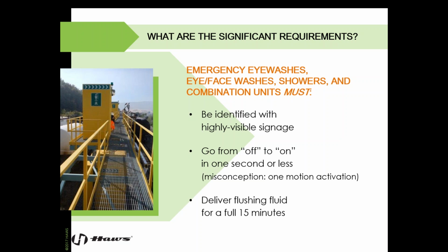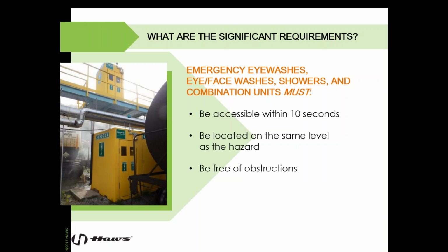All equipment needs to deliver flushing fluid for a full 15 minutes. That's a lot of water. So one thing to consider that's not touched on in the standard is the drainage aspect. So for example, with a combination shower and eye face wash unit running for a full 15 minutes at approximately 23 gallons per minute, there needs to be somewhere for the water to go. So keep that in mind when you're purchasing or installing new emergency equipment. And Samantha, on that note, we do see a lot of those in the field, specifically in hospitals where they'll have issues testing because they can't flood out the floors beneath them.